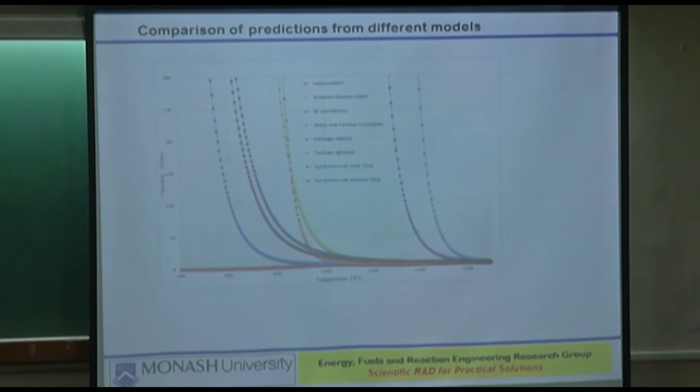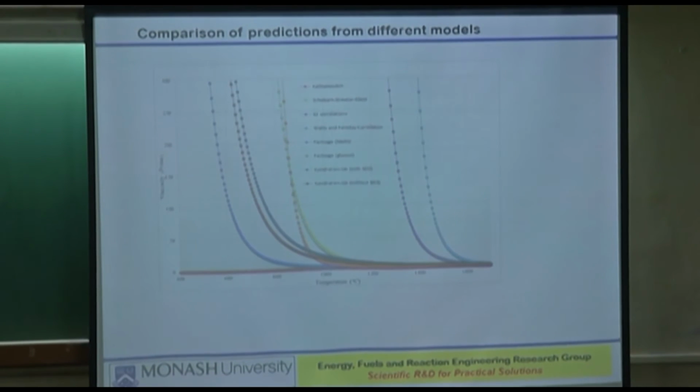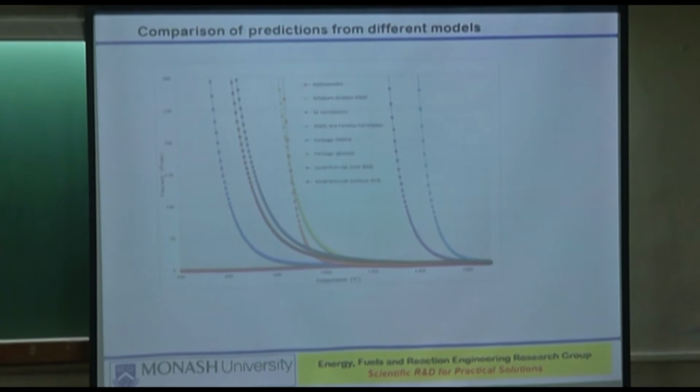So, that ash fusion temperature falls in between these two, temperature wise. So, you can say that yes, it will melt at that temperature, but is that good enough for gasifier use, for use in design of the gasifier? Because what I said, the melting is a function of temperature and time.